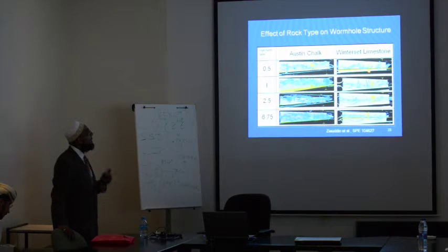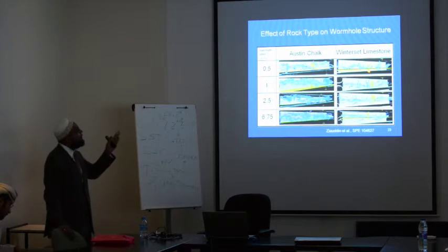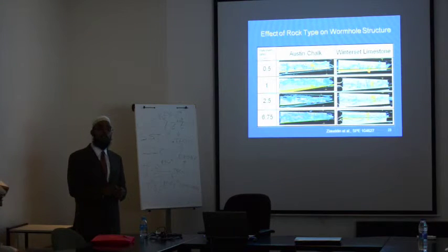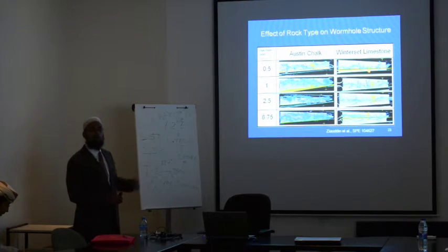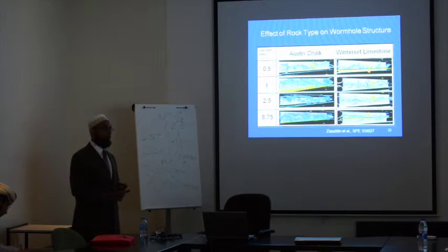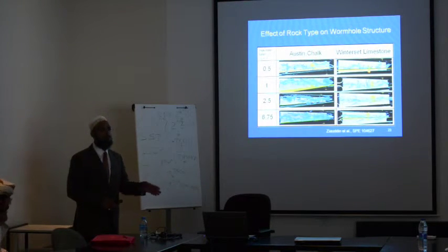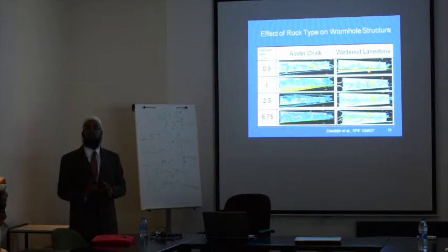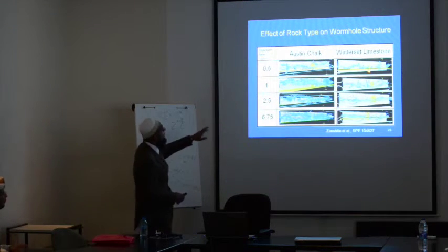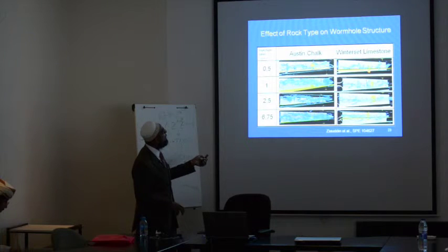Okay, I'll skip that. Now, pore volume of acid to break through measures how much acid you need. I've shown two different rock types over here which have very similar pore volume of acid to break through, right? They're both almost 100% calcite. They were both acidized at the same temperature, 150 degrees Fahrenheit, with the same acid, 15% hydrochloric acid. Same core length, 6 inch by 1.5 inch, right? Everything is the same, and the injection rates are also the same.